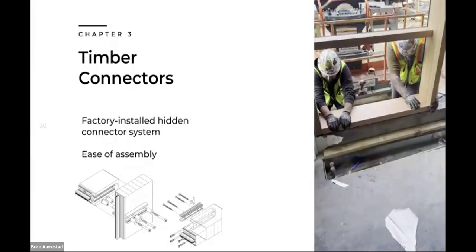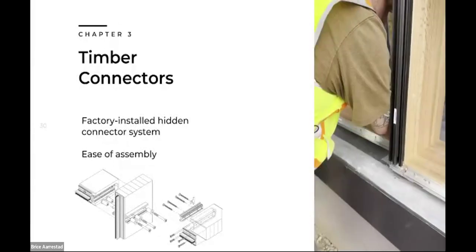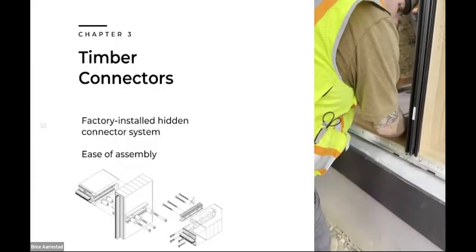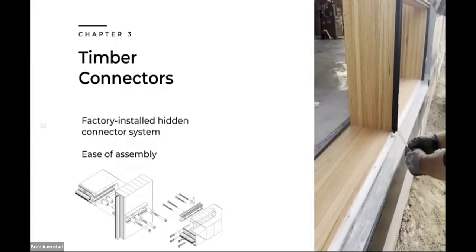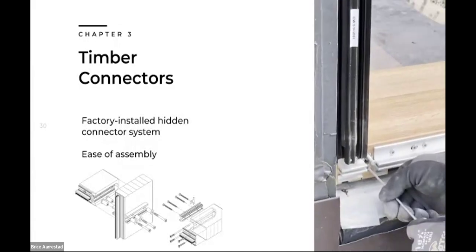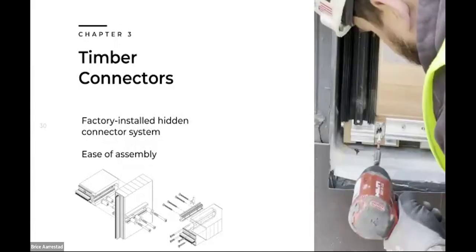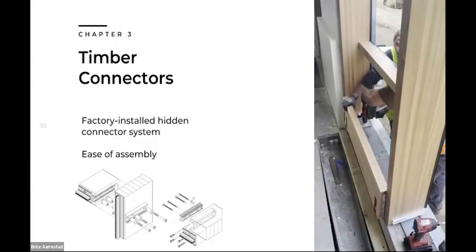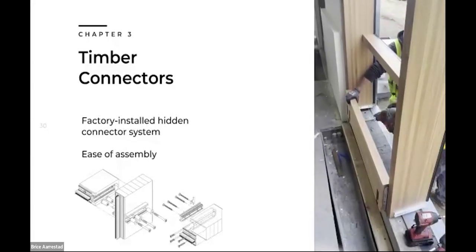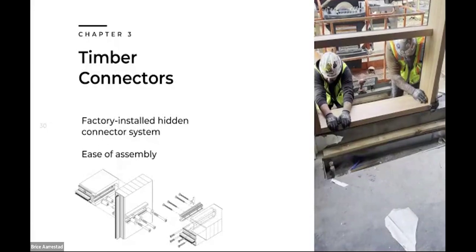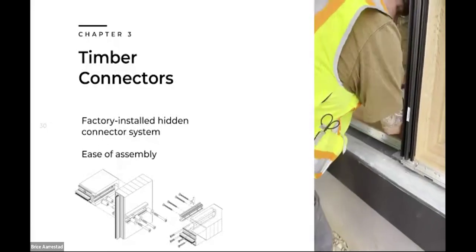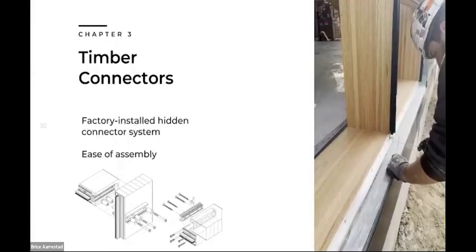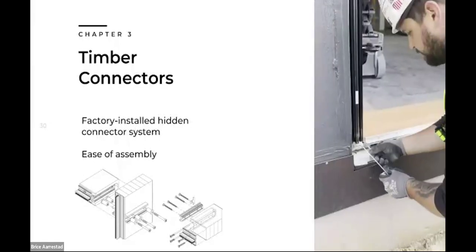Even in this video, you're seeing the sill is the full depth of the system, and then there's a transom or a horizontal member that is slightly narrower because it's not doing the work of resisting the wind load. It's really there to hold the glass in place and resist the gravity load of that glass. So let's talk more about these anchors.